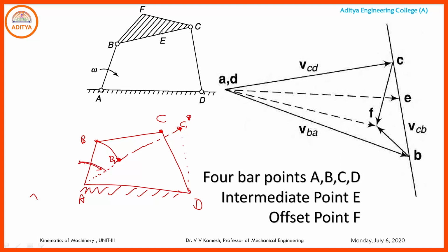That's why the easy way is that the relative velocity of B with respect to A can be known from the velocity component, but the direction of angular velocity simply alternates, clockwise, anti-clockwise. So the crank is rotating clockwise. That means this will be rotating anti-clockwise. Again this will be rotating clockwise, right? So from C, this is a very small angular displacement. This is a much bigger angular displacement. So the angular displacement itself tells us this is rotating in the anti-clockwise direction.